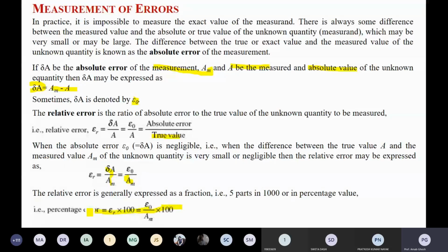So three things are there. One is called absolute error. Next one is the relative error. The formula of the relative error is given over there. And final one is your percentage error. Percentage error is nothing but the percentage of the relative error. These three errors are most important, and in all the portions of the measurement you have to calculate the absolute error, relative error, and the percentage error. Absolute error comes from the measured value minus the actual value or the reference value or the set value. It may be reversed also, in which case the positive error and negative error definitions will be changed.